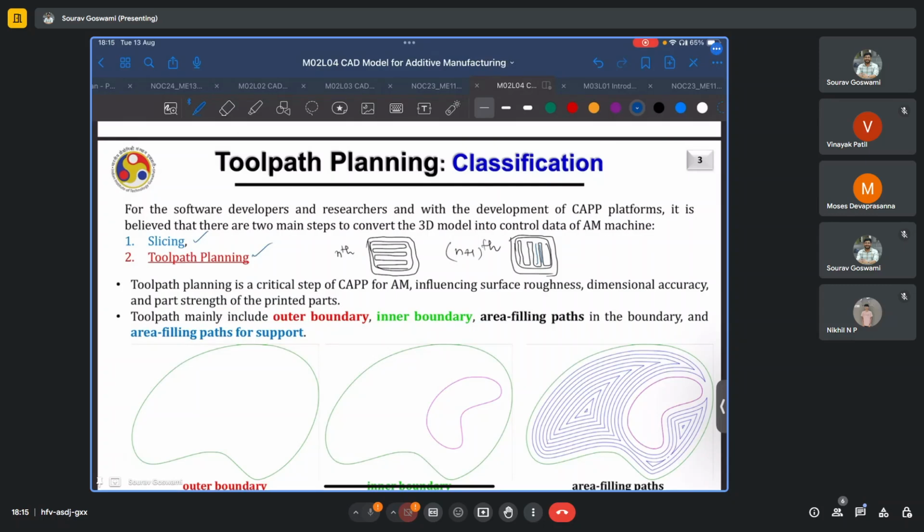So let us continue. One more thing is, when you build the very first layer, which is in contact with, say, your build plate, you'll often find that the parameters that are used for the first layer are different compared to the parameters for the rest of the layers of the bulk. One change which you might have come across is that often in the first layer, for example, the print speed or the infill speed is only 90% of the specified value.